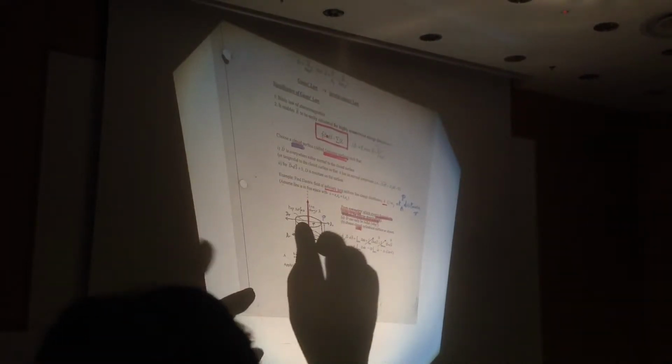What is left is the outside, where the flux is normal to the curved surface. At the given distance r, D_r has the same value. Therefore, the flux coming out of the curved surface will be D_r multiplied by the area of the surface of the cylinder. The surface area of a cylinder is very easy to find out. Take a pair of scissors, cut the cylinder and open it up. When you open it up, this side is 2 pi r and the length is L. Therefore, the area is 2 pi r times L. So the net flux is D_r times 2 pi r times L.